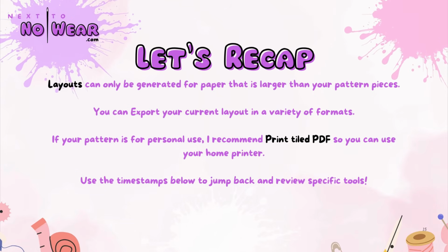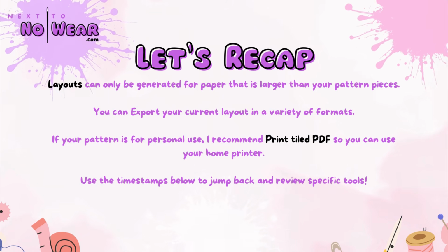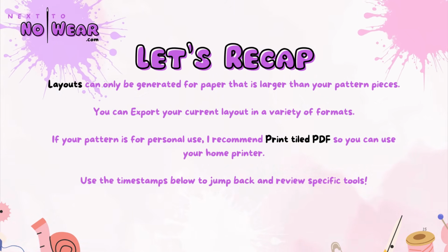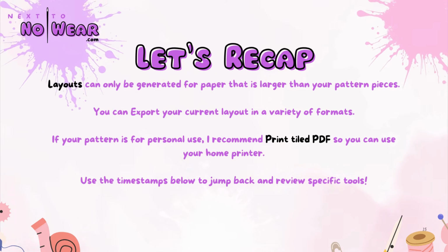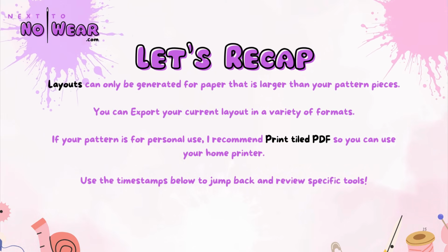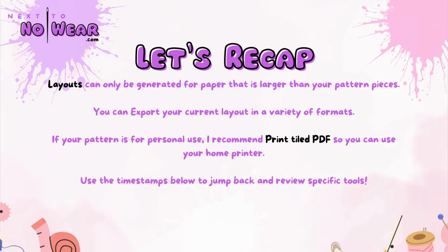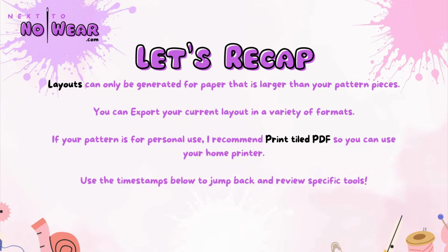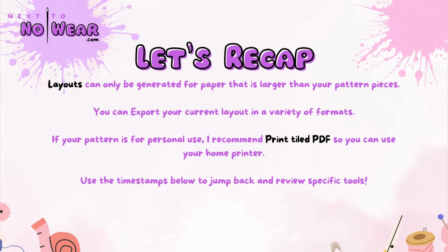Let's do our final recap. Layouts can only be generated for paper that is larger than your pattern pieces. You can export your current layout in a variety of formats. If your pattern is for personal use, I recommend using the print tiled PDF so you can use your home printer. And again, you can use the timestamps to jump back and review whatever you need through this whole process.